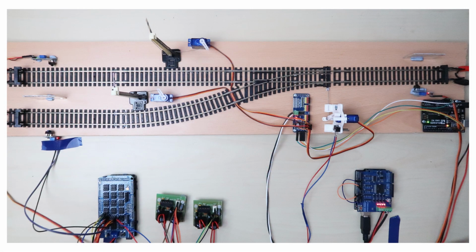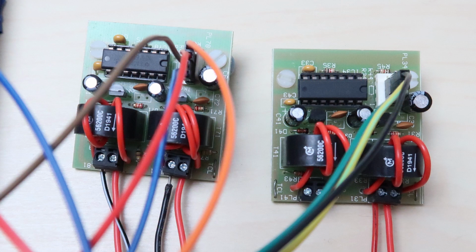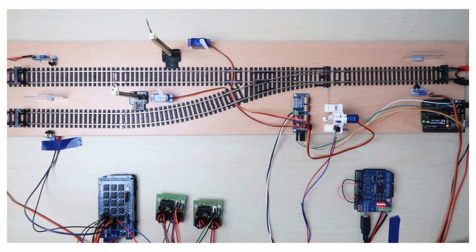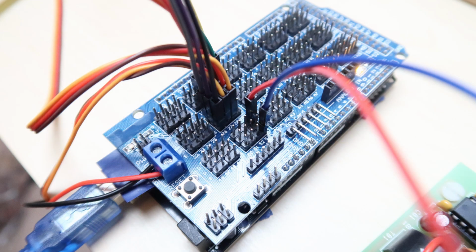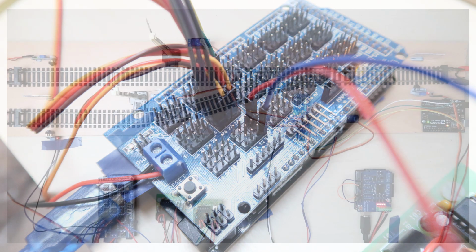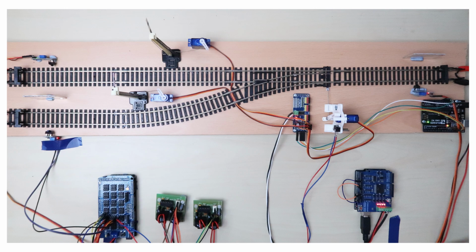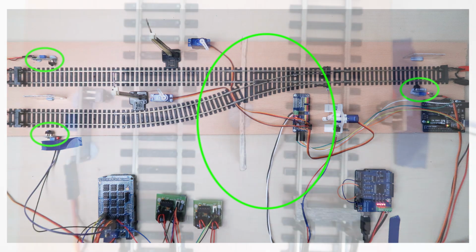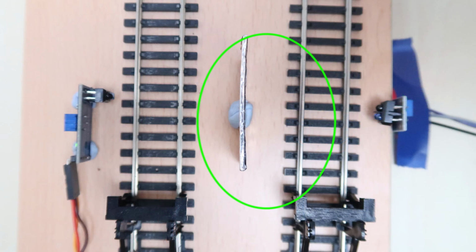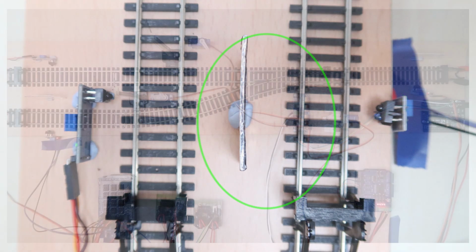Each of those 3 feeders is going through a block occupancy current sensor, so we can sense if anything is drawing a current in that block. Those current sensors are connected to the sensor hub, and again, this should be familiar if you've watched my video on how to build the sensor hub. Also attached to the sensor hub, we have 3 infrared sensors, which have been set up at the end of each block by the buffers as gates, which will detect when the train comes to the end of the line.